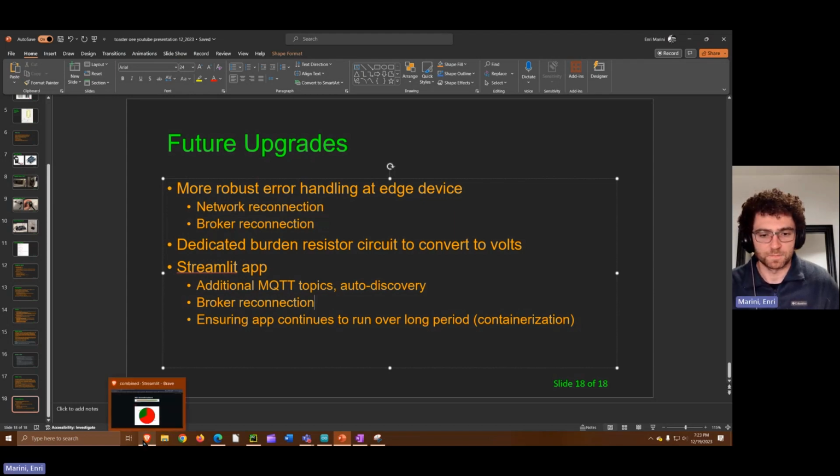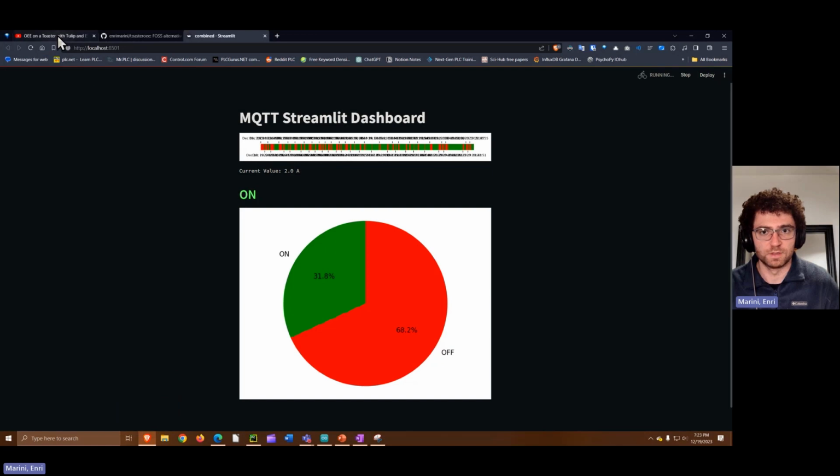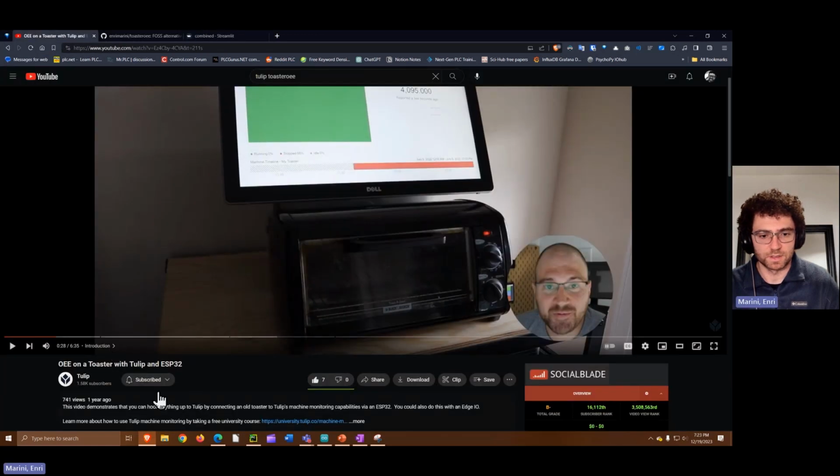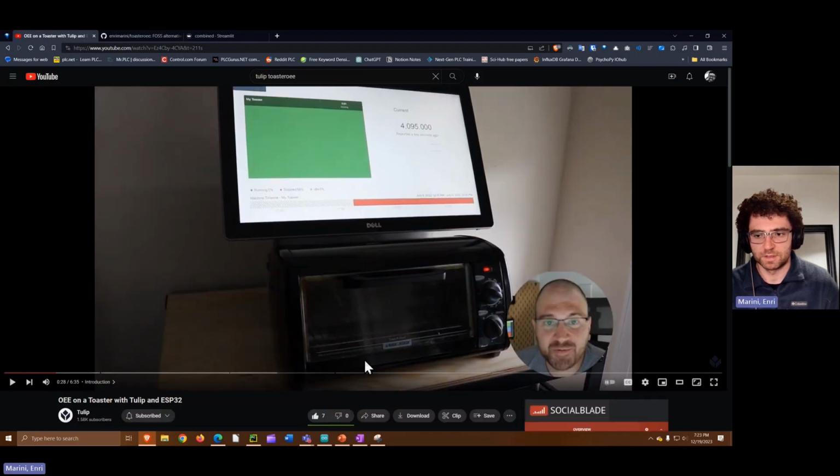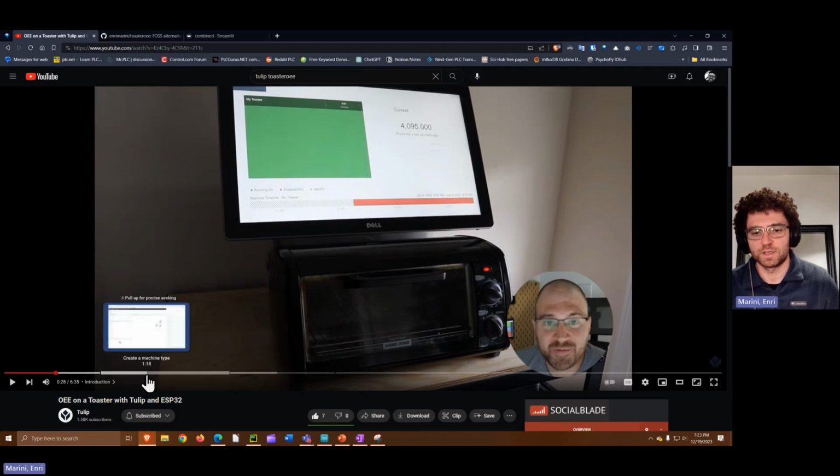And I will show you the link to the example that I took the motivation from. You can see they have a similar manual switch operated, and here again, as they're showing the electrical current values, that's not a true current value. The way they had the board lined up, there is no burden resistor circuit.